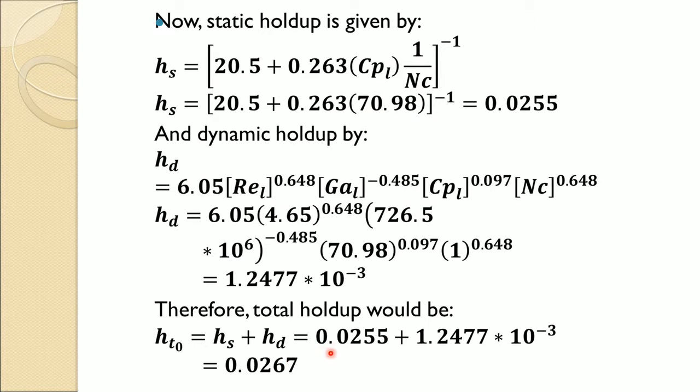of liquid in the blast furnace, and this would be constituting almost 5% void fraction. It would be occupying the space, and even a 5% space, when it is reduced, is going to change your gas velocity and other parameters substantially, and that is why this importance of this liquid hold up.